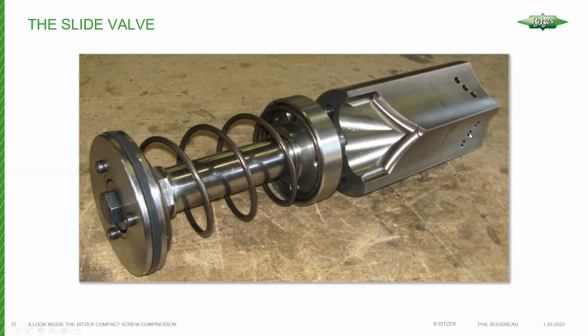So unlike fixed unloading type compressors where their positions are fixed, the slide valve is dynamic, you can move it around. The economizer port moves with the slide valve, so we don't have that limitation where, when you're economizing, you have to disable the economizer when your slide valve is running at a low capacity condition. So I wanted to bring that up because that's another feature of compressors in general that have slide valves. With the BITZER compressors, all of the compact screws have this type of capacity control, this slide valve, and this kind of economizing approach is used whenever desired.